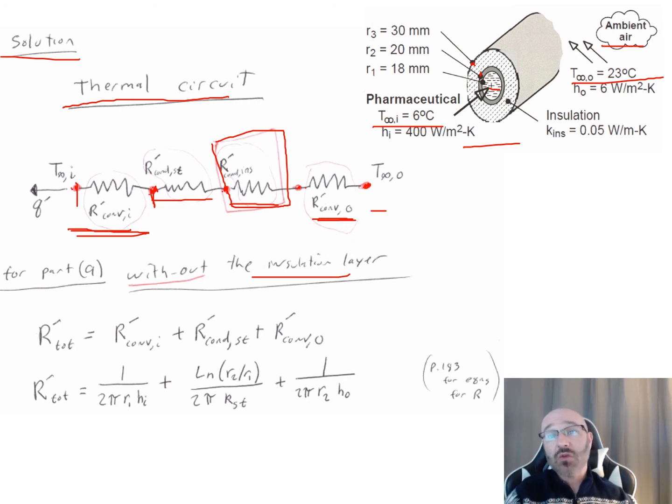if I try to do this all in one, I've done 2 things here on purpose. 1, I did these thermal circuits all in one to show you it can get a little confusing. And 2, I did not draw out my 2D layers from my 3D diagram here to drop down those nodes, so we can see it is a little bit confusing, especially if there were even more layers within this composite wall, of where my nodes are and what those physically mean. Whereas if you have that 2D representation, you can draw a line straight down at each of those interfaces, each of those surfaces. It's a lot easier to create this thermal circuit right here.